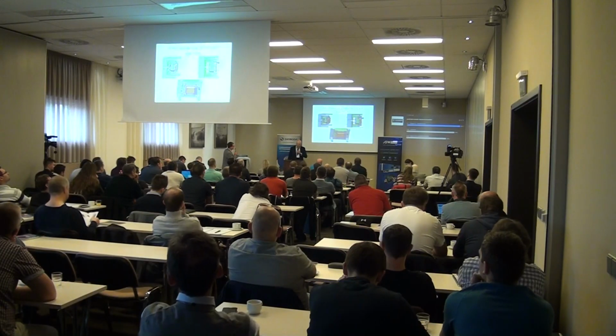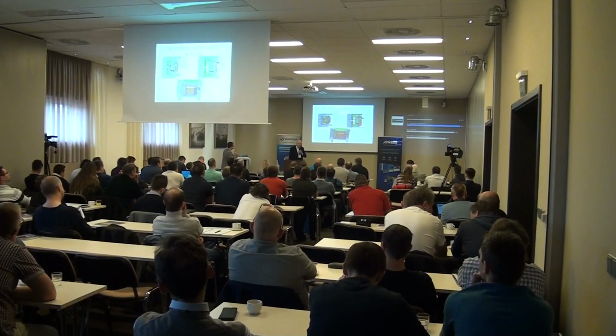So the next important point was to remove the hydraulic, but somehow we need to realize two-stage ejection. Because normally when you move a slide, and you don't have a second ejection, parts stay between the slides and the cavity core. And when the slide's coming back, the part is smashed. So in this case, we need to have a second movement to remove the part from the slides.